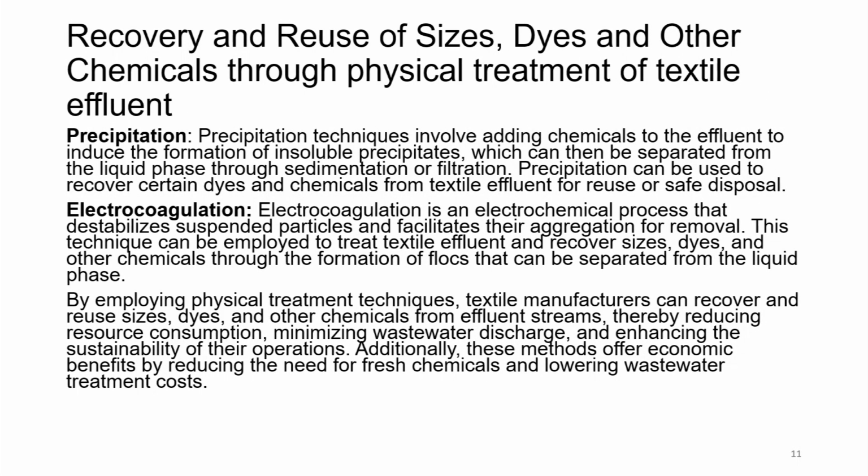Precipitation. Precipitation techniques involve adding chemicals to the effluent to induce the formation of insoluble precipitates, which can then be separated from the liquid phase through sedimentation or filtration.